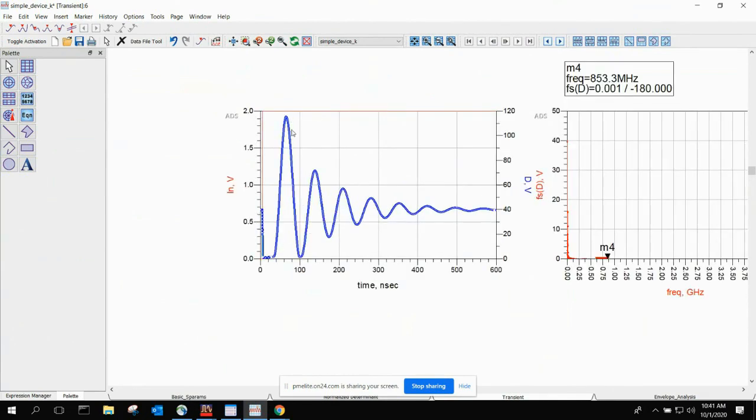But if you remember back to my slide that I talked about with the left half plane and the right half plane, you'll quickly identify that this ringing is decaying to zero. This is an instability, but it's existing in the left half plane. So this will decay to zero. And I can also detect that, of course, in the frequency domain and show you that it's somewhere around where that negative value was. So I want to make this point because it's really important.